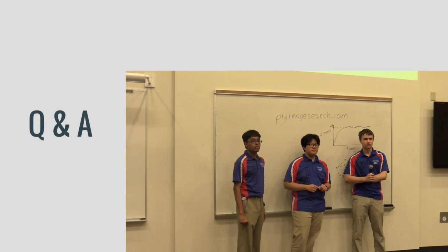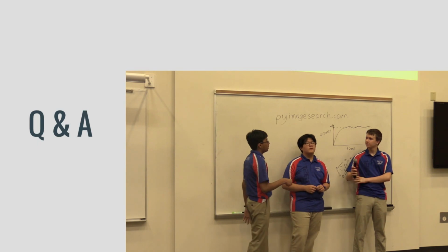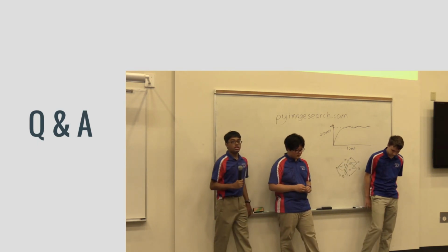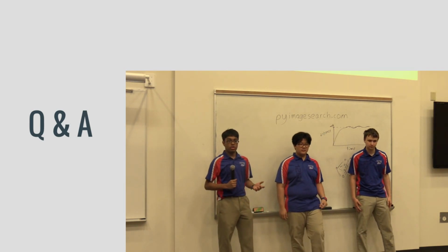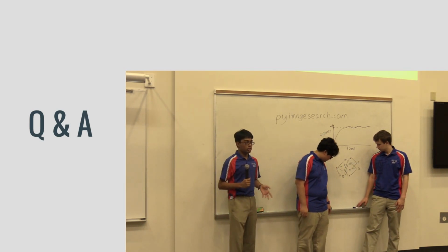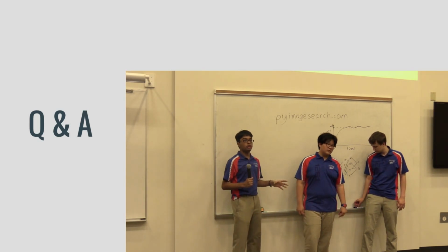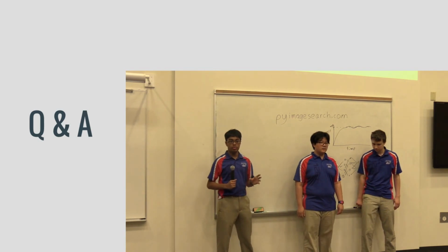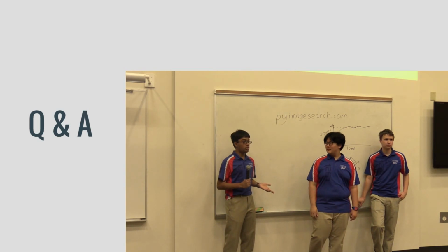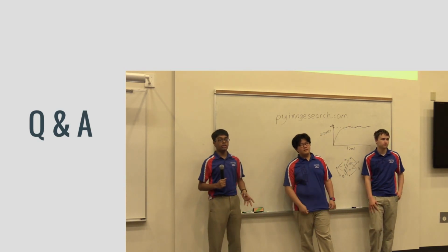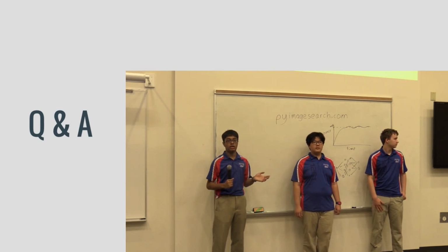Minimum timing frame? You had to be there for at least a half second. Oh yeah, you want to talk about it? Yeah, so one thing we did to solve that problem with the floodlights confusing our vision tracking system was that we made sure the robot would only shoot if it could see a particular target for, I believe, a quarter of a second or half a second, because when it saw the floodlights, it would occasionally track them, but it wouldn't track them consistently.